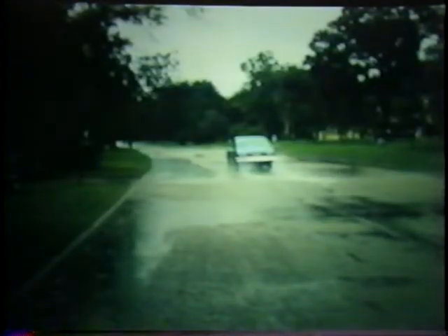An uneven pavement surface can trap water and cause hydroplaning. Roller coaster pavements cannot accommodate drainage and allow water to collect. Drivers don't know that the water hides depressions in the pavement. When entering these water-filled depressions, drivers can unexpectedly lose steering control. Inspection of the roadway during or immediately after a heavy rainstorm will identify sections that drain poorly, so that corrective